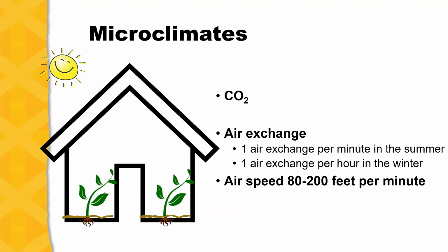need to grow. So that's why we have here that during the winter months, you want to have 1 air exchange per hour. And what that does is that once the CO2 levels are depleting here, remember that outside in the environment, the CO2 levels are 400 parts per million, right? So what you do is that you open up the vents and you slowly let some of that air in to bring in fresh CO2, but it also pushes out that air that has low CO2, right? And it replenishes the air inside CO2.